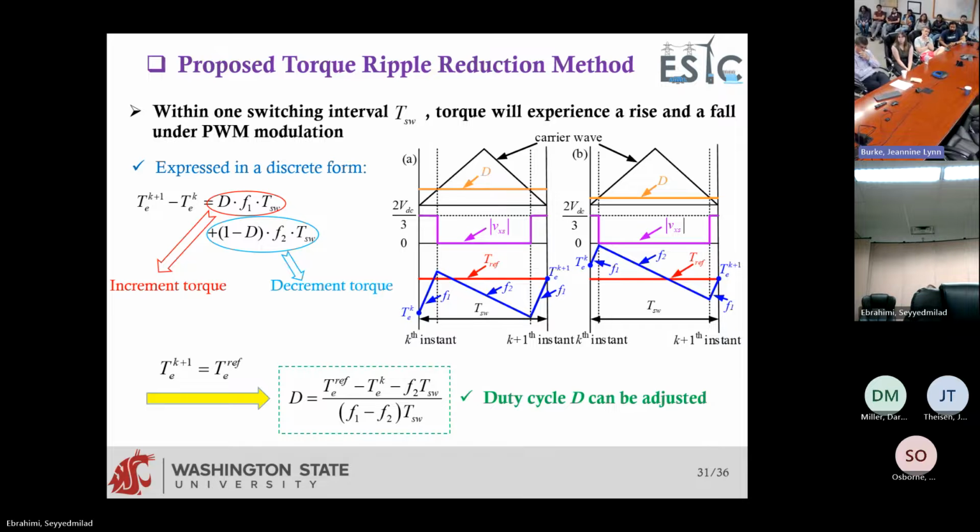So when this is higher than the carrier, it turns on that phase, connecting phase A, let's say here, to the DC terminal. Then it disconnects because it's going to be off, and the current goes through the lower diode. And then it turns on again like this. This is done at every switching interval, a high switching frequency interval. So this is about how we do this, and of course, this is done with my DSP to have this high speed.